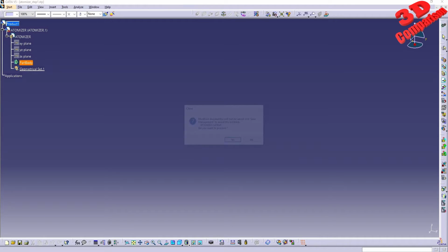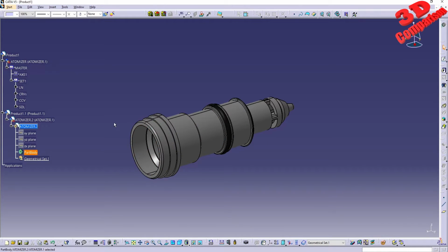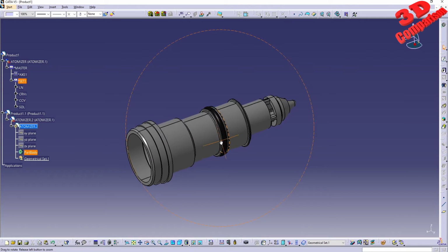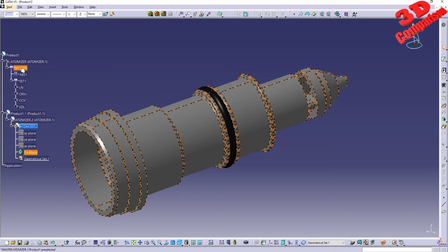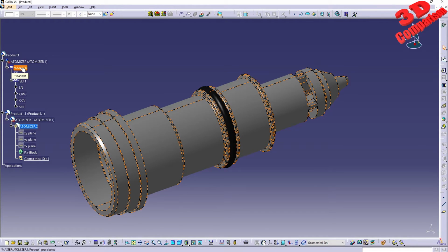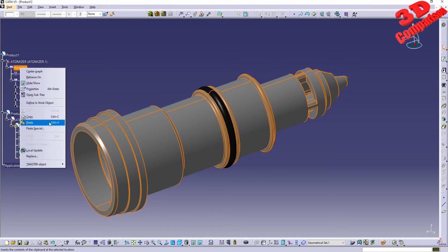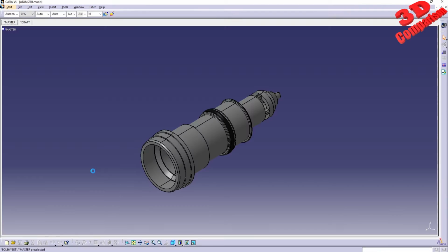Therefore, the technique that we can use to have this properly converted, so we won't use the step, since this is a legacy file, is to make use of the conversion available within CATIA V5. So I'm gonna go back over here on the master file, right click, go to master object, and I will have this open in a new window.